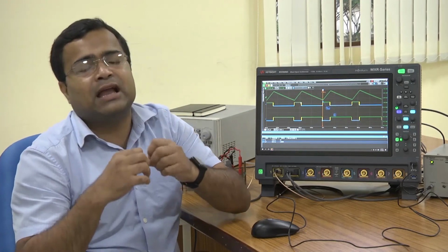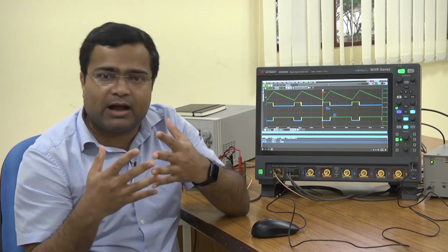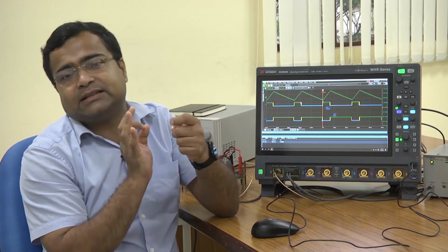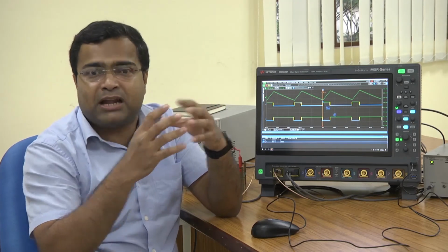That's why you need a dedicated digital channel, and that is one of the purposes of using a mixed signal oscilloscope, because in the FPGA, what I have started demonstrating, and I will be demonstrating in more videos, if you encounter some problem in the digital code, you want to debug it. That means you have to pass some of the digital signals through your IO pin, and these digital signals are logic signals which only take 0 and 1. So you can take multiple such digital signals.